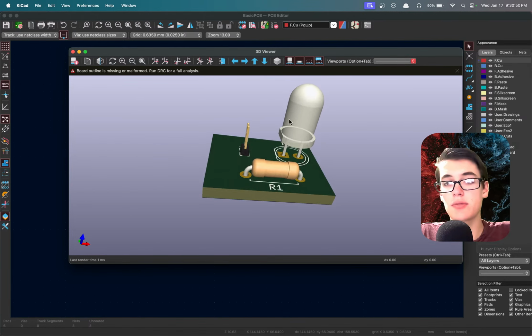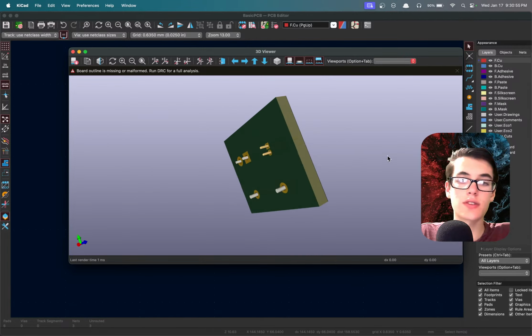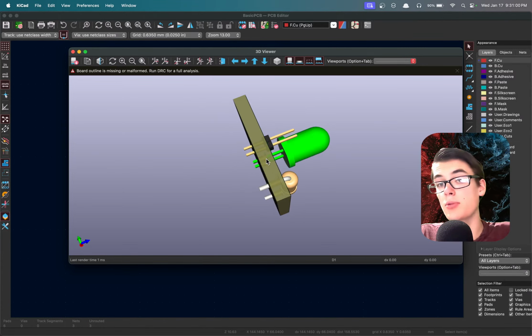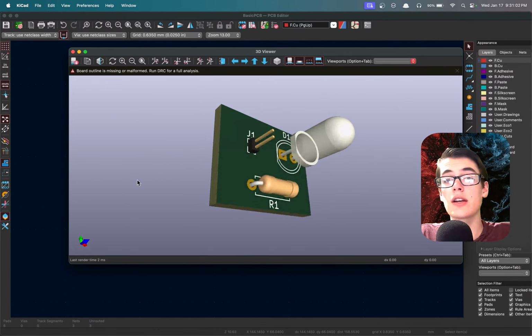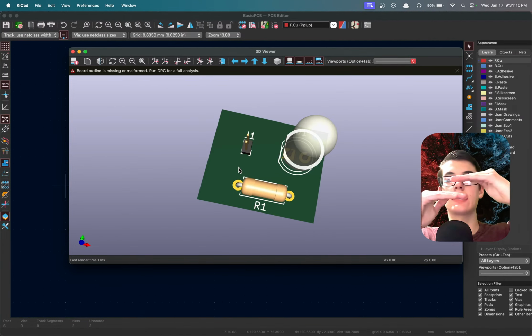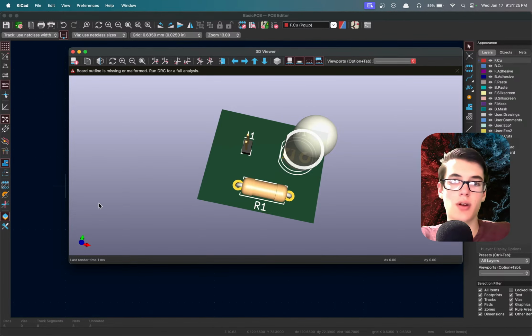Yeah, so those are the main layers we're looking at here. Now, the layer count that your PCB has is the number of copper layers it has. So if you had another copper layer, that would be like having another set of wires disconnected from the first set of wires. So there's two copper layers that aren't connected except in some places, so you can have traces cross over each other. If you just have one copper layer, everything is on the same plane, so you can't have a trace cross over another trace, or they would touch each other, and that would probably cause a short or something.